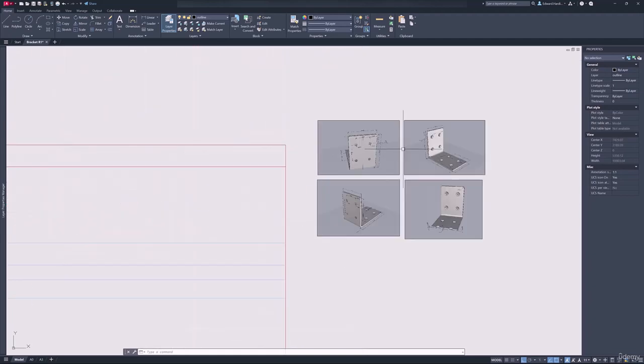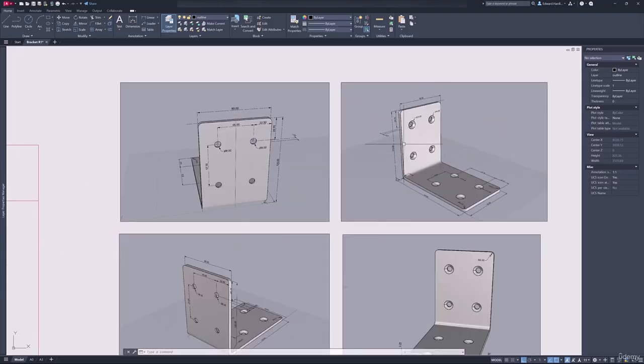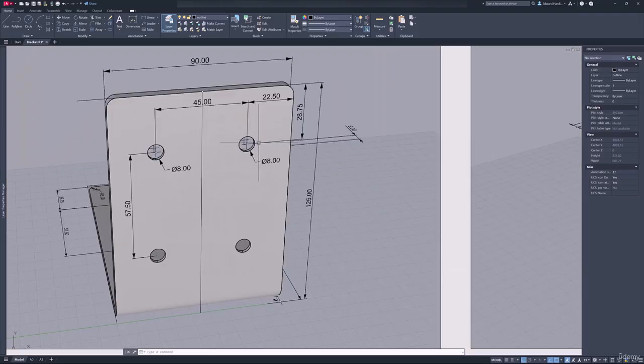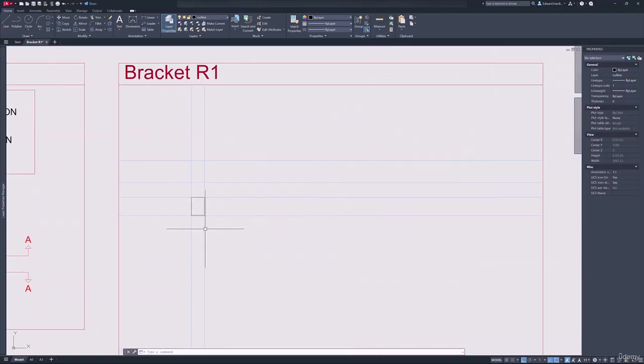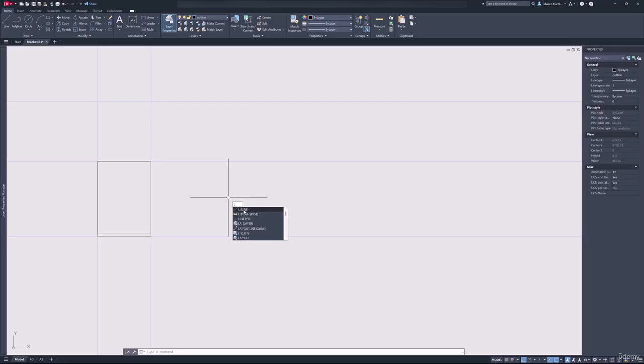What next? I think let's go ahead and start our holes. I think that's the next thing to do. So I think the first thing I want to do is work 28.75 millimeters down. I want a line down there, so let's do that. So again, I'm going to press L and select line, and I'll just snap to our construction lines, bring this down, and go ahead, type in 28.75 and click enter. And now without pressing escape, I'll bring this line over like this. I'll left click once and I'll go ahead and press escape. And there we go.